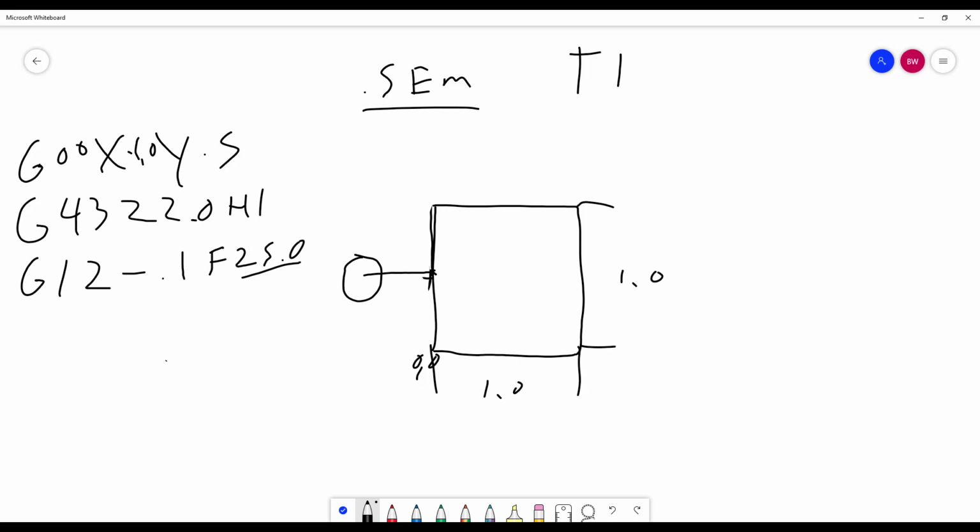The video title is something like Mastercam cutter comp types. This would be the control method. The wear method would be if you are using comp G41 or 42 and numerically offsetting the cutter in the code. But we're going to use the control method. So then this line now, assuming we're 1 inch away, -1, is going to be